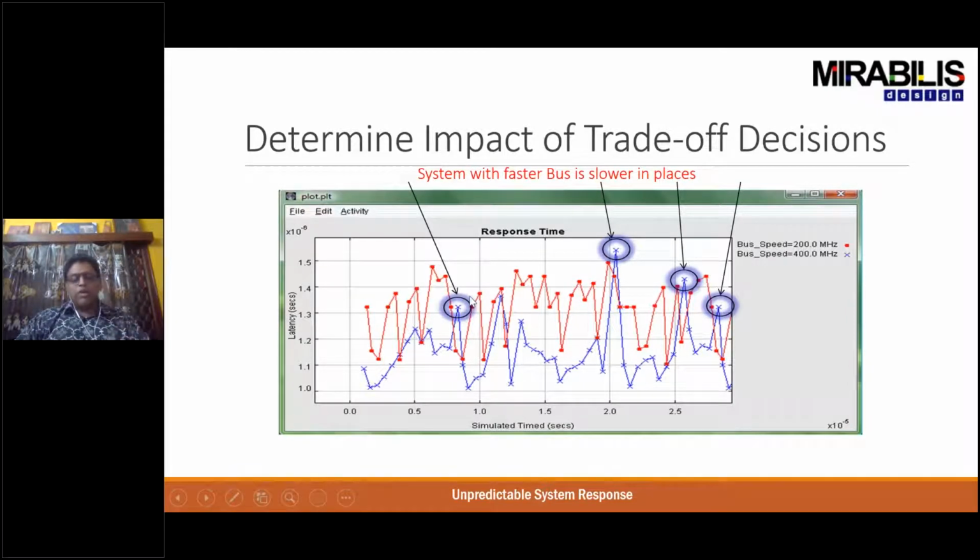So when you overall look at this design, you find that the 400 megahertz based architecture provides almost a 50% plus range from your worst case to your best case execution time. So if you take that as a major discriminator, you're going to find that the range of the 200 megahertz is actually much better. So in this particular case, the 200 megahertz architecture is preferred, and that's what will be considered in this design.